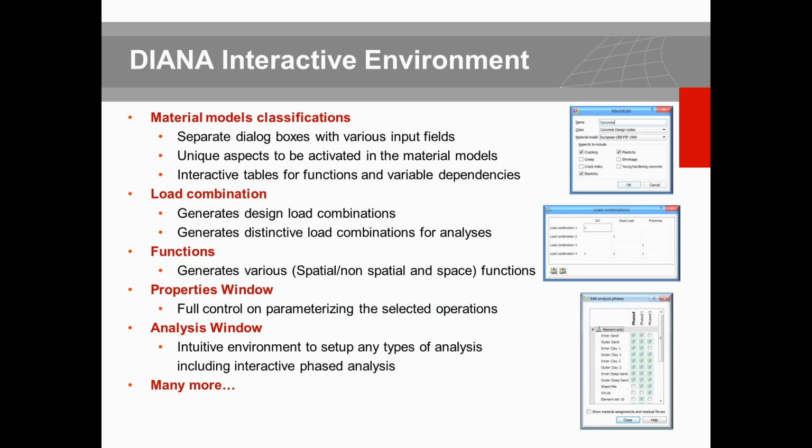So here you can see, based on the type of aspects that you want to consider in your material model, for instance, if it's considered with heat, or for the Rayleigh parameters, the associated parameters become active. If you don't check this on, those parameters are off. So this way you work with the optimized, minimum material inputs which are associated to that particular analysis.